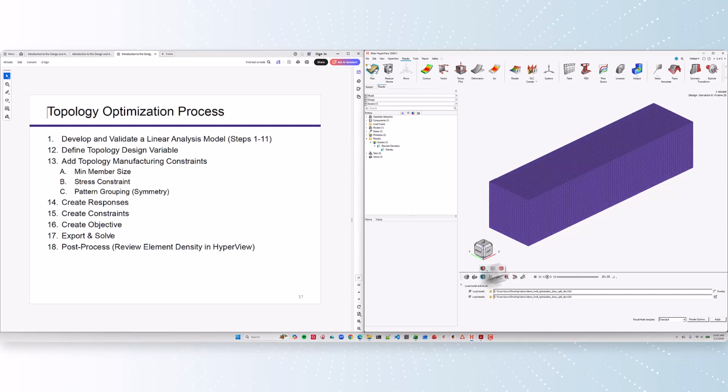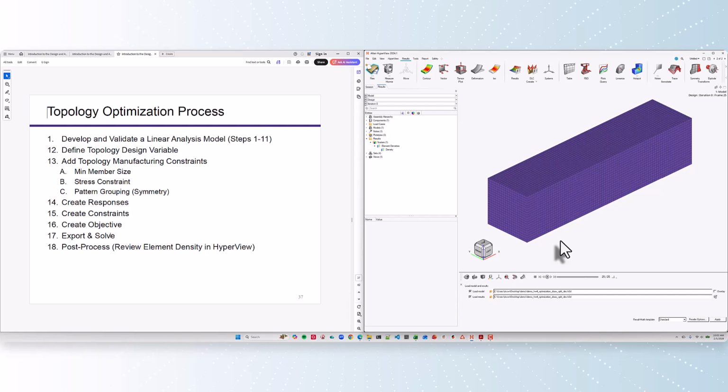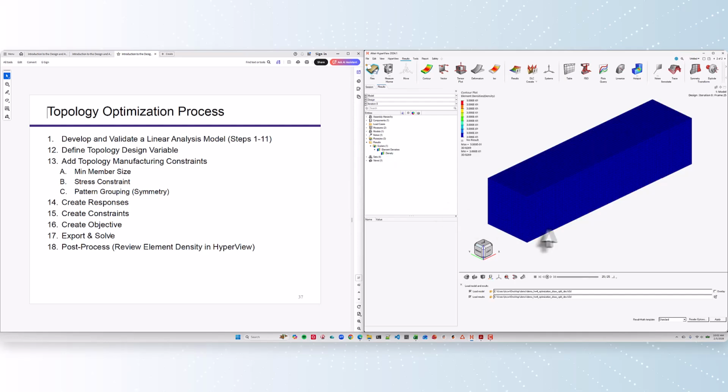So first thing I'll do is just show the element edges, and then I will plot the density. And I think a student here had an issue where it said, yeah, it only shows me 0.3 for everything. And that's because we're in a post-processing mode called an interpolation mode, which is what I was doing before, just dividing a single result by 25. But that isn't what we have. We have actual runs. We have actual number of runs. And so we need to go into what's called a transient mode.